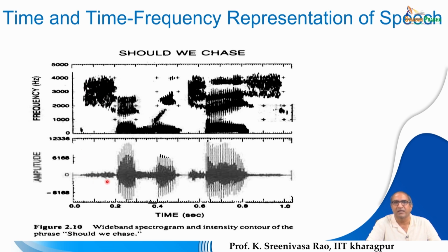And then for a, because of the shape of the vocal tract, you can see the energy is concentrated at a low frequency, then over here, and then over here. So there are three frequency ranges that capture most of the energy. Here this is your F1, maybe around 300, this is your F2, maybe around 1600, and this is your third formant, F3, about 2400, something like that.